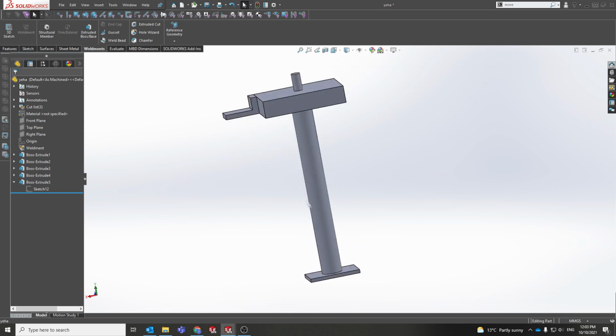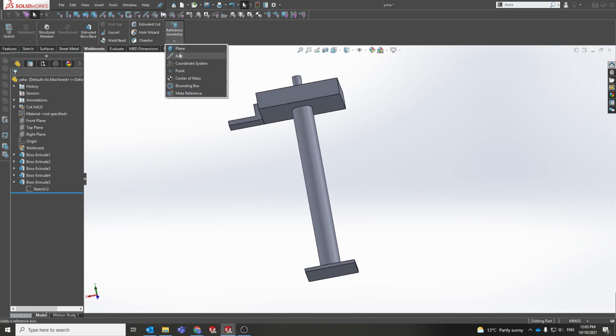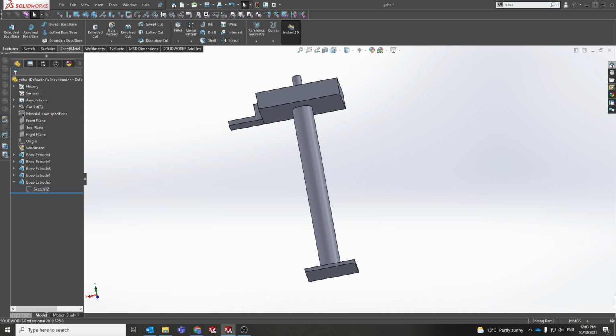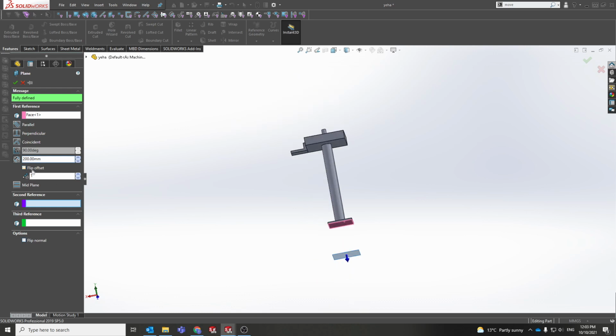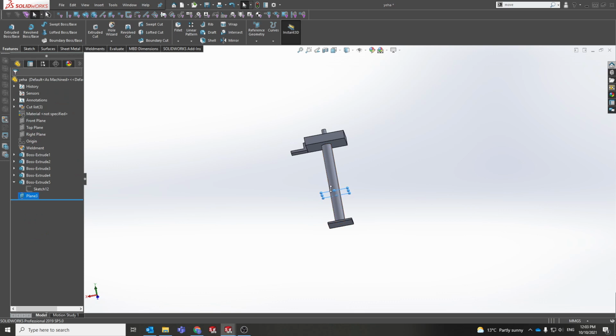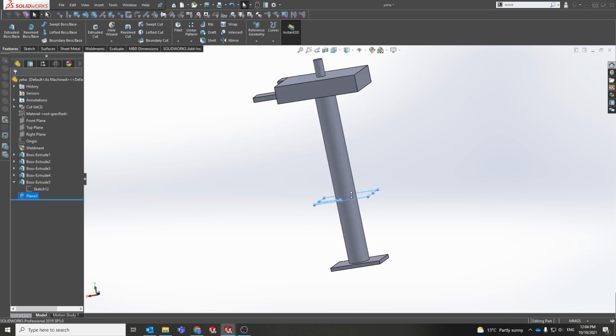Now let's say I needed to split this up for a 3D print or whatever. Let's say my 3D printer can only print up to here and then I need to do the rest. Well, what I can do is go features, geometry, plane off here. Let's say my bed's only 200 high, so I can only print up to there and then I need to start again. So I've done that and then I'll go split.